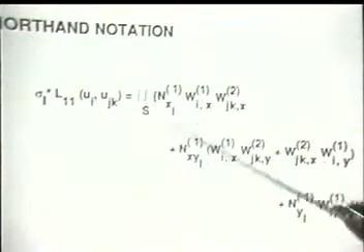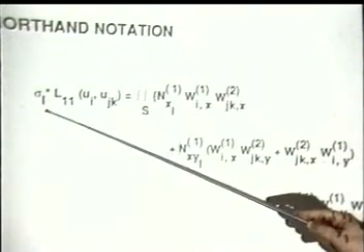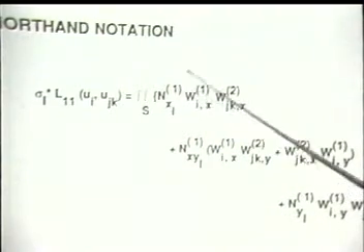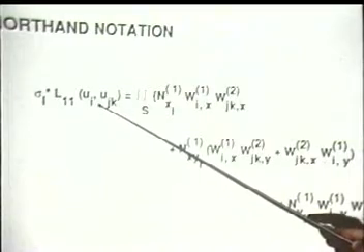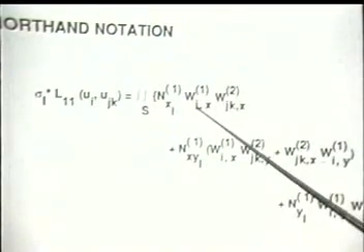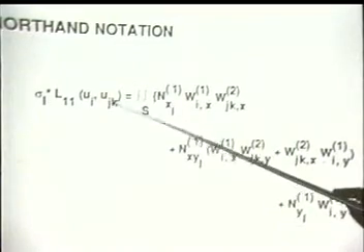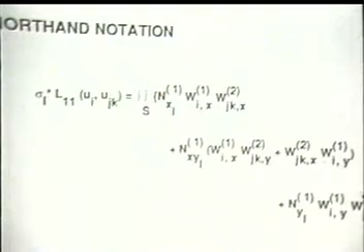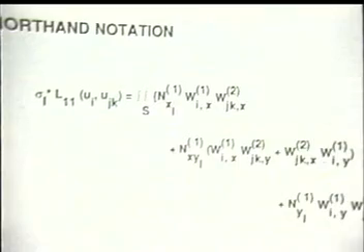It depends what you put there. If you recognize that, that is the stress resultant of the buckling mode. Stress resultant, stress resultant, stress resultant, super 1, buckling mode. If you look at that, that is the out-of-plane displacement of the buckling mode, right? Derivative of it, okay? Those. And that double subscript, that is a second order field in derivative forms. So this shorthand notation stands for a rather extensive expression.